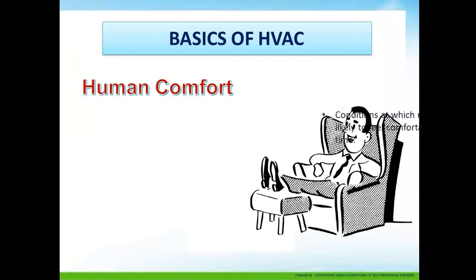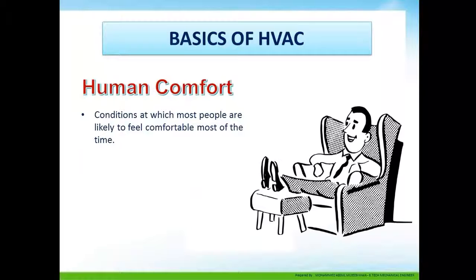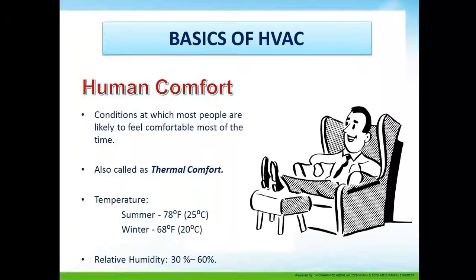Human comfort. The condition at which most people are likely to feel comfortable most of the time, also called thermal comfort. The temperatures are 78°F in summer and 68°F in winter, with relative humidity of 30 to 60%.